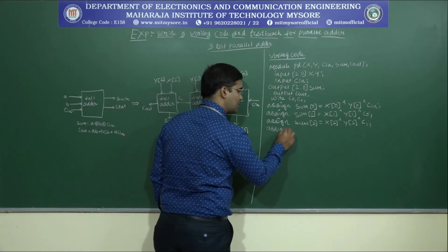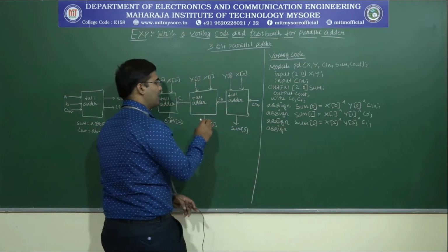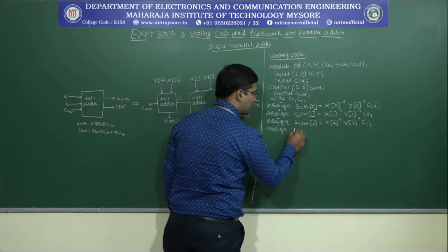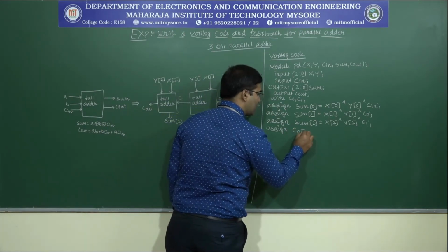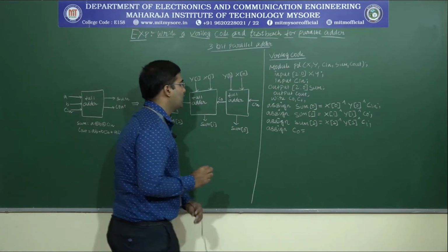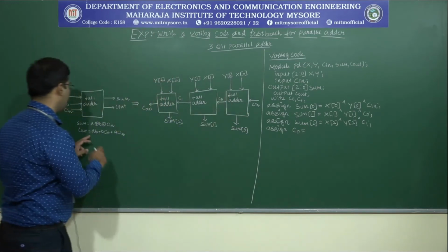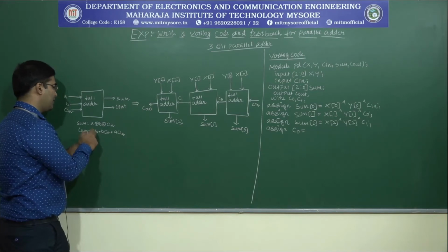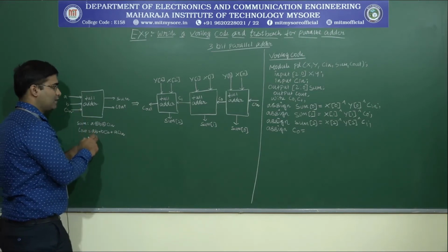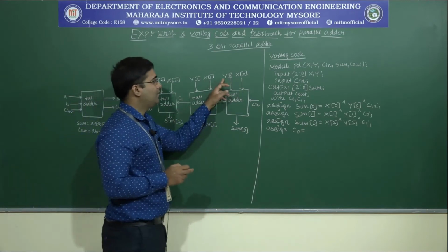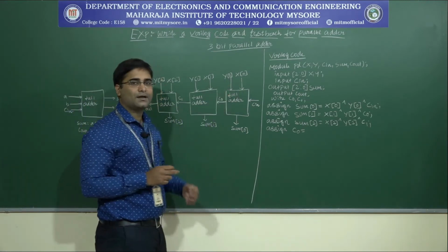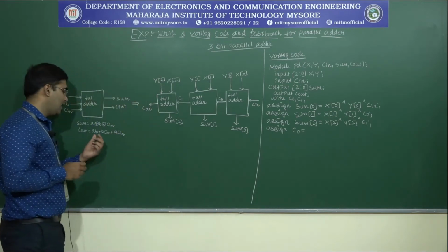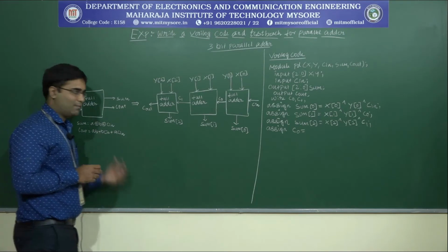We will use an assignment statement again, for sum and carry out. What we have defined is C0, the combination of the variables with respect to the inputs. Here we again have the combination, but in terms of the operators of Verilog, where the AND and OR are replaced.